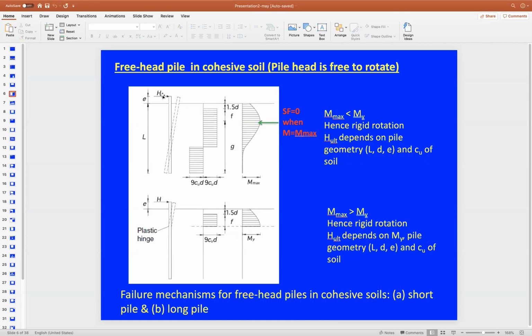The equations you will have here are according to the static equilibrium laws. You're going to have one equation from the equilibrium of the horizontal forces in the problem, and another equation from the sum of moments at a certain point in the problem.